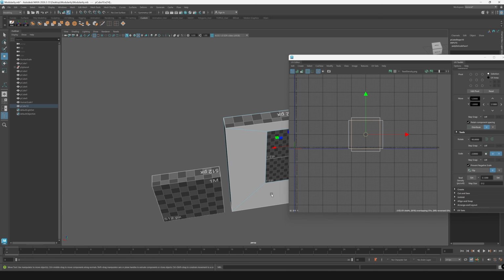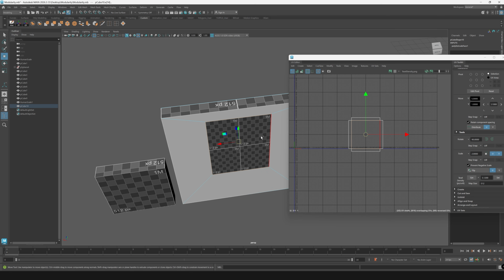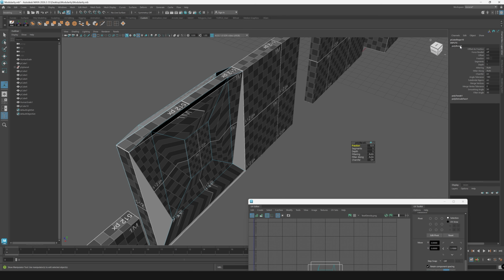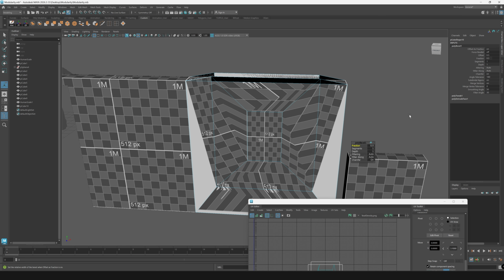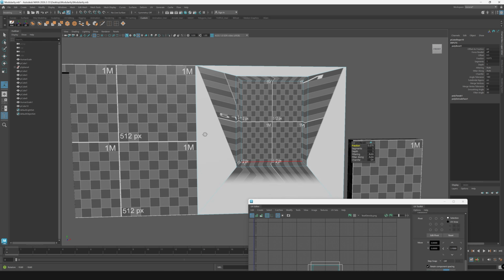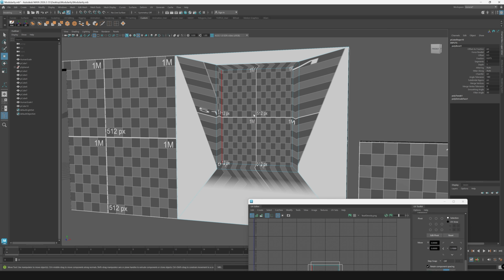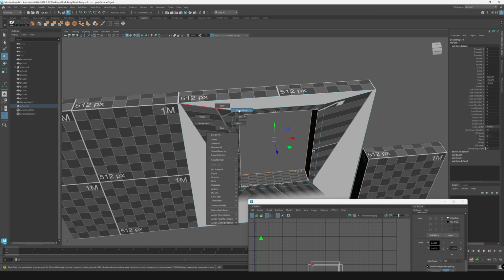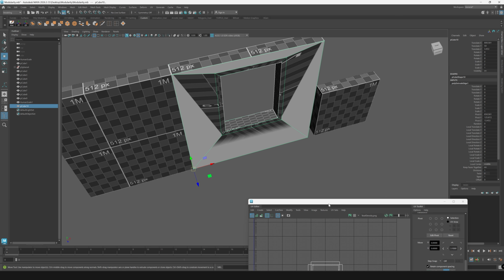Now select these guys and do the same thing and create a trim around the edges, a border, if you will. So let's do a bevel. And I need to, of course, make some changes to the bevel because it's beveling way too far out. So let's change the fragment size to something kind of closer to what I want. So maybe 0.075. Perfect, exactly. So now, delete. So we have something exactly like this.